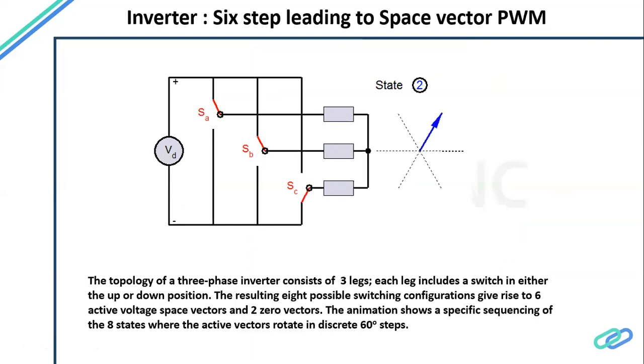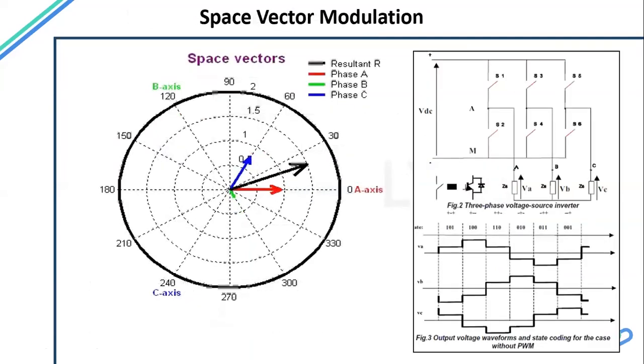So this is typically 6-step control, which we try to implement at very high speeds, because that gives us very good voltage, but a lot of harmonics at that speed. But there are a lot of versions that come up, and it drives also to the space vector, right? So this is a birthplace where the space vector is evaluated. So you can see this is where instead of switching to the 6-step